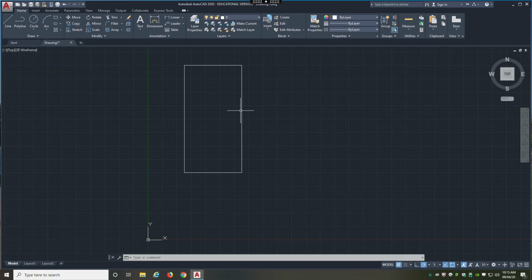Make sure you finish through the command and hit enter before you see what's happening, because it can be very easy and very frustrating that after you input your X value and you're working on your Y, it does something completely crazy, and it doesn't look anything like what it's supposed to. So make sure you finish the command. Okay, rectangle tool one more time. Now there are additional options. Again, with many commands, there are additional options in the command line, so you can practice with those.